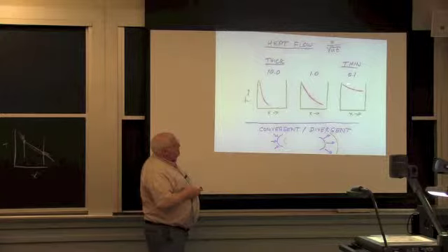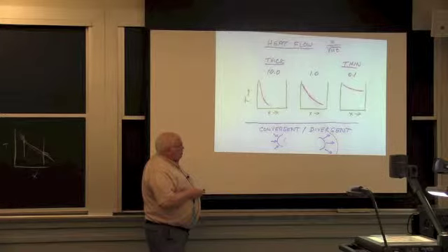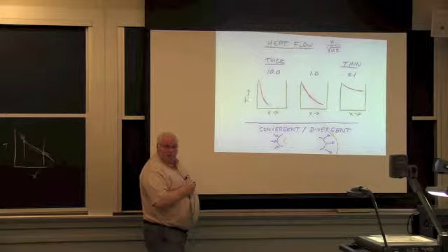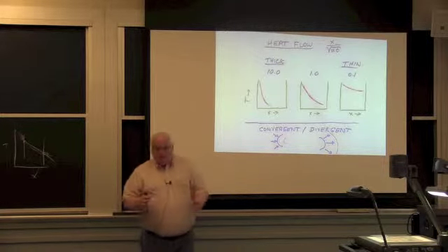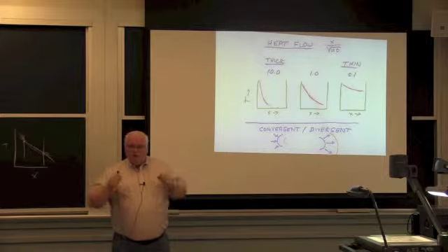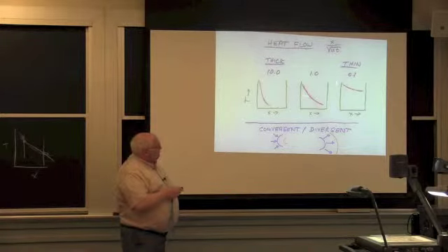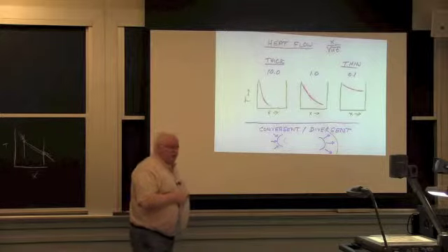If it's a Fourier number of 1/10, basically the heat has started to accumulate on this other surface and starts to flatten out the gradient, which slows down the heat transfer into the material, because the gradient here, Fourier's first law, says that's the rate of heat coming into the material. Here it's a very steep gradient, okay? When you first put a cold thing into an oven, the heat going in is very rapid. As it starts to warm up, the heat going in decreases over time because the gradient at the interface, at the surface, decreases over time.